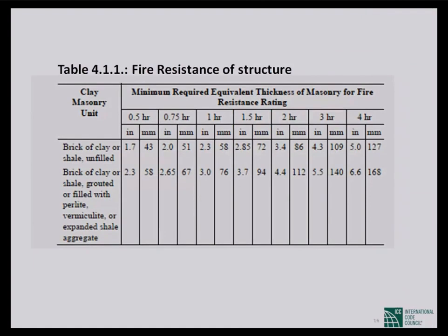Here you can see the brick, but unfortunately these are all hollow brick. Somehow it was missed in the BNBC. There is no data about the solid brick, but for the details you can see ASCE 29. So any data you need for the solid brick, you have to go to ASCE 29 because it is referred by BNBC for detail of other properties of the brick. This is something missing from the BNBC for the solid brick.